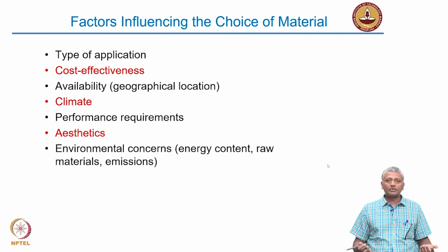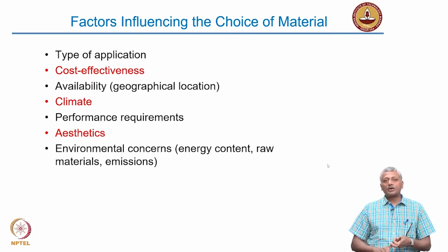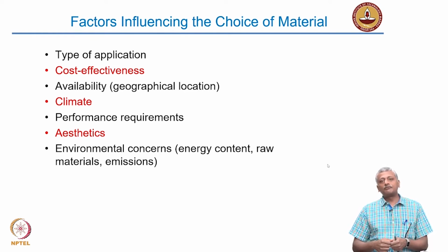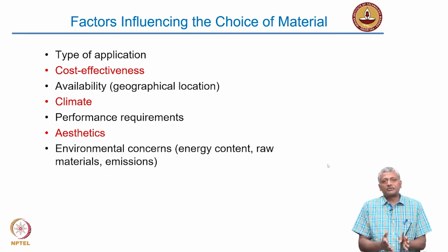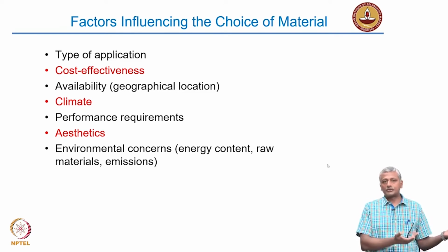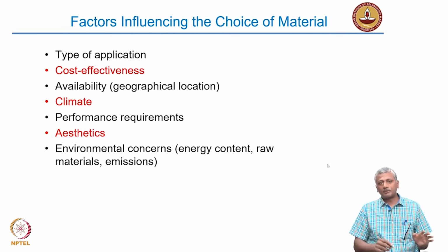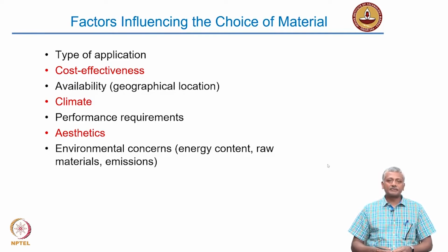So it can actually function for an extremely long period of time, but however, in modern structures we employ concrete in connection with steel reinforcement. And steel obviously has a tendency to corrode. You can't stop that. It will corrode eventually. Okay, so you can only design a structure for as long as it takes for the steel to corrode. If you design a structure with plain concrete, it may last for a very long time, just like your stone and lime did. Okay, so there is no problem with that. However, when we start using steel, the service life of the structure is shortened because of the time to corrosion of the steel.